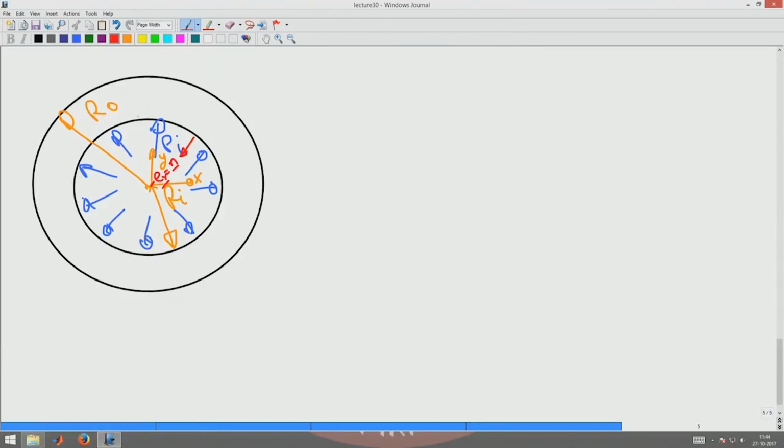So, this stress is sigma RR stress, or I can more formally derive the boundary condition as T of negative ER is given by plus PI ER, because it is acting along the ER direction. Now, T of minus ER is sigma RR 0 0, 0 sigma theta theta 0, 0 0 sigma ZZ.